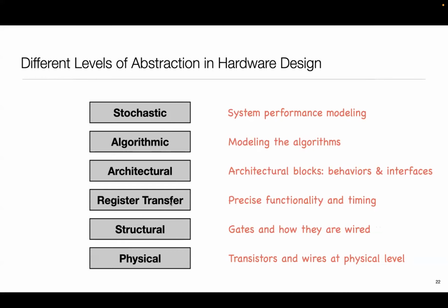Then we combine these things into what is called register transfer. This is where we begin to worry about functionality at a higher level, in a very precise manner, and timing. Almost all digital systems are designed using what is called a clock synchronous way of designing things. That is, there's a clock which is ticking at a regular rate, and operations happen conceptually at a tick. We don't care about in between. As long as an operation I start at a clock tick finishes by the next clock tick, I'm good to go.